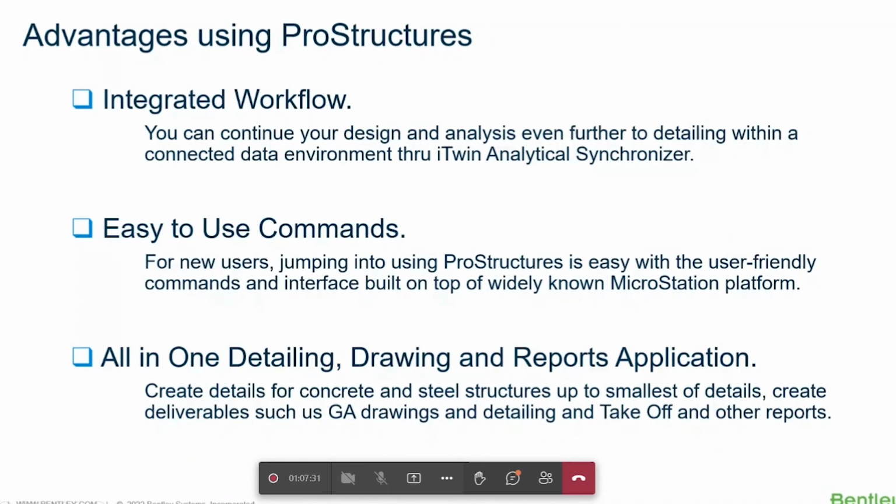Since yung workflow natin pinakita ko sa inyo kanina, using iTwin Analytical Synchronizer or yung ISM, Integrated Structural Model, madali lang pong mag-transfer ng model from your STAAD.Pro papunta sa ProStructure. And even vice versa. If ever meron kayong mga revisions, mas madali pong mag-change ng analytical model. So, ganun yung workflow. Mas integrated siya.